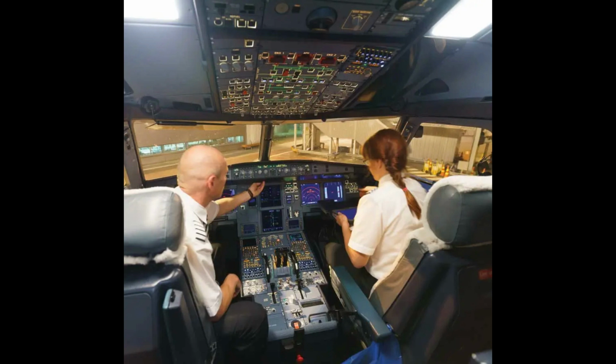Managing the flight versus actually moving the controls allows more time for 1. Programming. Especially when flying under IFR, changes to a route are inevitable. Even when the pilot is proficient in using FMS/RNAV, this task requires focusing some attention on the programming task. The FD/autopilot keeps the aircraft on the programmed heading or course and altitude while the pilot makes the necessary changes to the flight plan. If programmed correctly, the aircraft maintains the correct track and altitude.